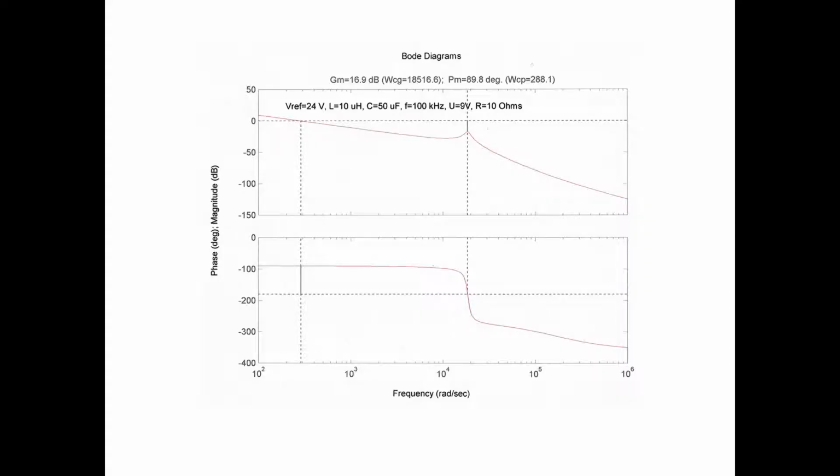So this would tell you at 10 ohms, which is the most lightly damped point in that, this says we have a gain margin of 17 dB and a phase margin of almost 90 degrees. So any control guy will tell you that's a super stable system. You're not going to be unstable. No worries. And they're right. The output's not going to blow up. Whether it's acceptable or not is another question. Okay, and that's what you got to think about. And so let's look at this.